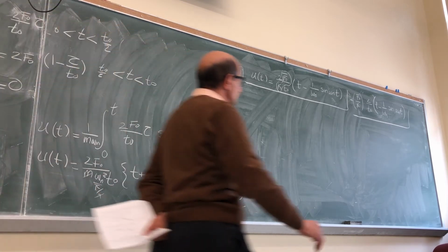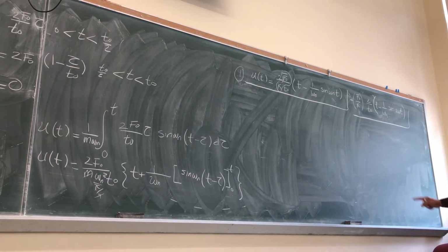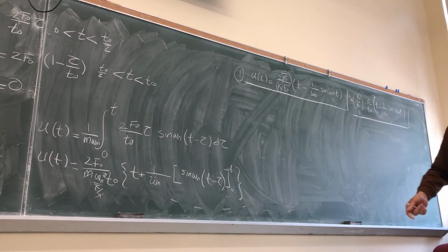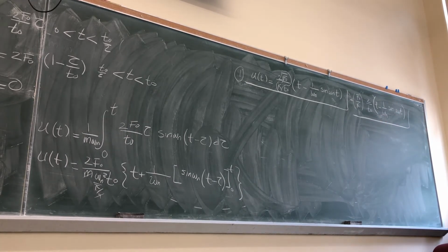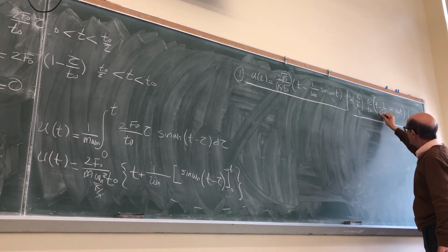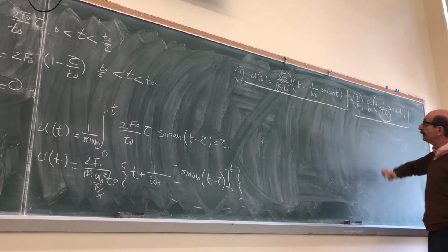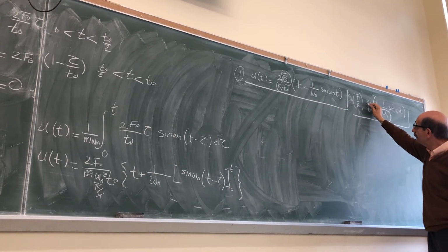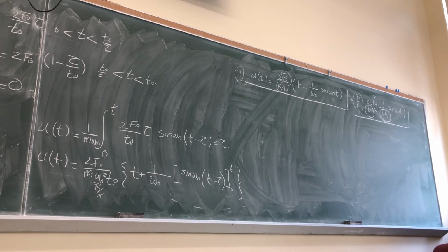Before I go any further to the other cases, I should point out an important observation that you can make also with Duhamel integral, or the response due to general loading. You always see that the response due to general loading depends on 2 important quantities. One is the natural frequency of the system, and the other one is the duration of the forcing function.